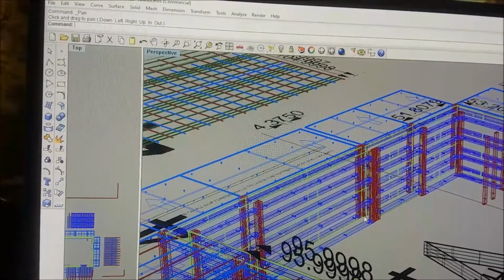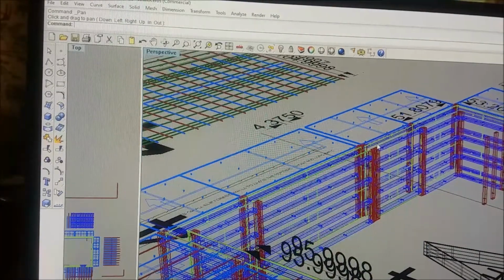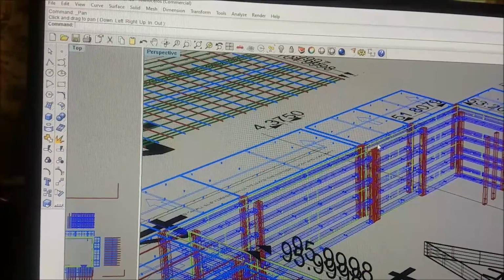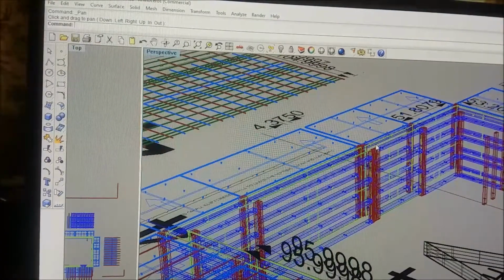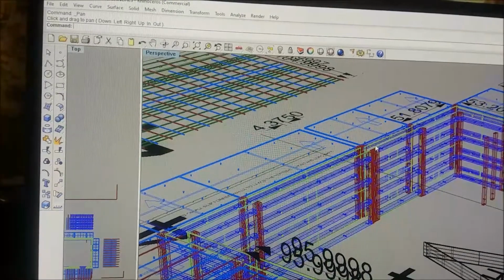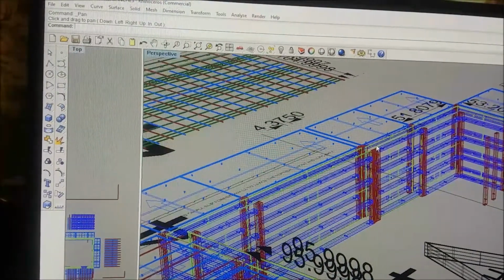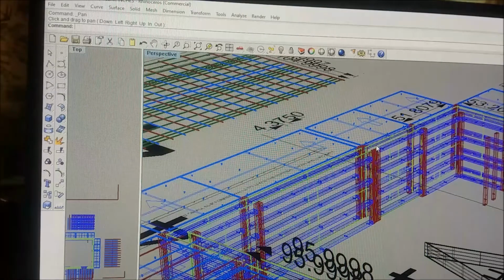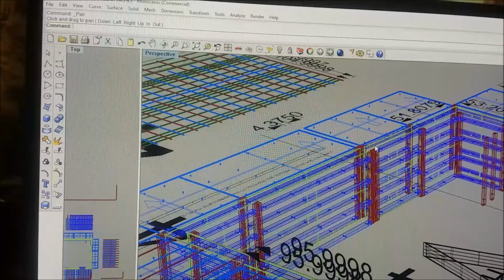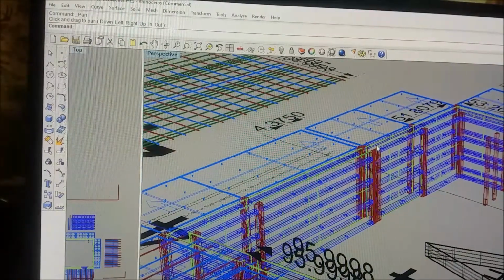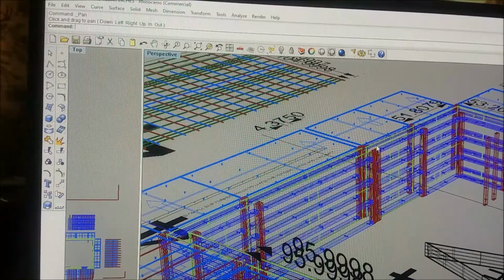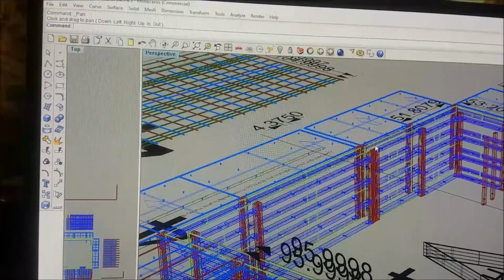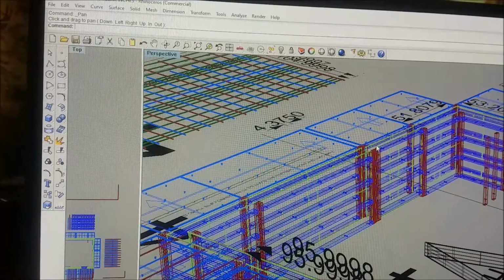And he uses a 4-inch thick wall, which is gracious and plenty for an 8-foot high house wall. We use 7-inch. And the reason is we were pioneering this in 2014. And you have to get past building inspectors and things for certificate of occupancy. And if we'd have done a 4-inch concrete wall, it'd have been gracious strong compared to a 6-inch hollow block wall, 3 to 1. But they're going to look at that 4-inch wall and say, no, I don't know about that. And I didn't want to have it already up and then have to argue with them or go to court or something. So I took a regular wall, added the recommended thickness of render, didn't bother with skim coat because you're not required by law to have skim coat. Come out to close to 7 inches. So we just poured the wall 7 inches.